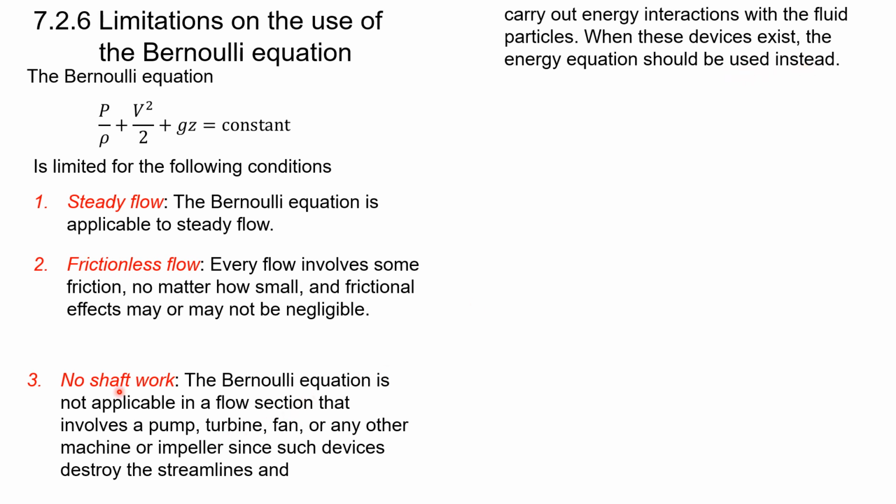So, no shaft work. Shaft work means some work is done to add energy to the system, like a pump. So normal flow. That's why in the house we use a water pump to increase the water pressure. Let's say the pressure in your house is low. Your father or mother goes and buys a pump, fixes it, and connects the initial tube to the pump. So the pump will help you to increase the energy in the flow.